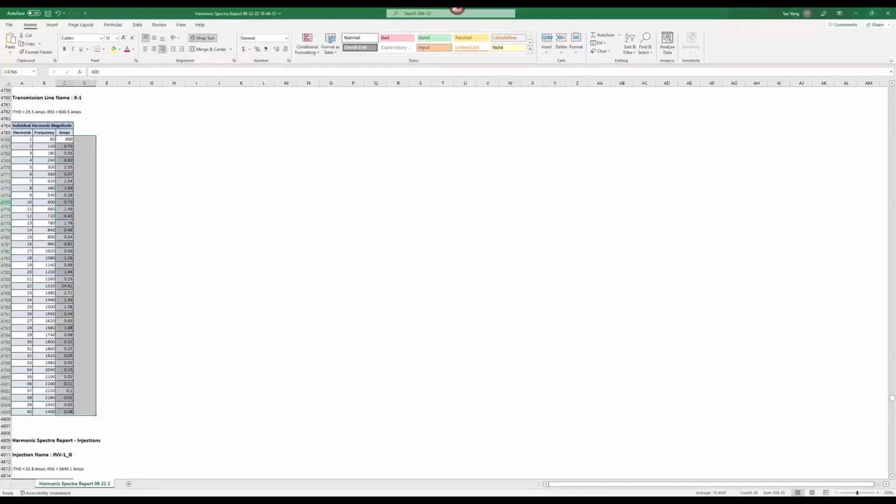What's the difference if we check harmonics using EasyPower or transient analysis such as EMTP? For example, will the filter sizing be different? No, they behave identically. It's just that EasyPower is frequency domain analysis, and PSCAD, EMTP-RV, or ATP is time domain. But at the end of the day, if you study harmonics within 50 Hertz, I would be really surprised if you can conclude something different by using two different approaches.